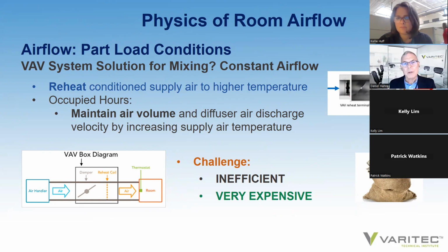I was at a chill beam conference and at the ASHRAE AHR Expo, I think it was in 2017, and Ken Laudermilk gave a presentation on the application of chill beams in healthcare. And he made the comment that reheat is one of the biggest energy penalties in healthcare facilities. So that is one reference. But who defines the air change rates in healthcare is ASHRAE Standard 170. And consequently, the only way to regulate temperature is to increase the supply air to the space in the event the space is overcooled. Did that answer your question?